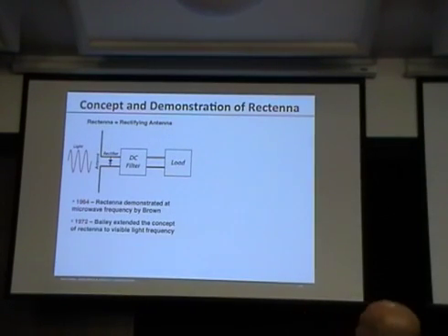All right. Optical rectenna. So the basic idea is that the optical rectenna is a device that takes incident light and runs it through a diode, right? Because we just talked about it. At some level, an AC alternating signal, like what you get out of the outlet, we know how to rectify that, make DC out of it. So light is no different, except it's much higher frequency, which means that we need a much faster diode.